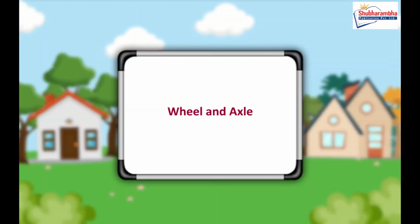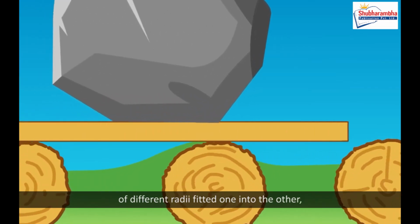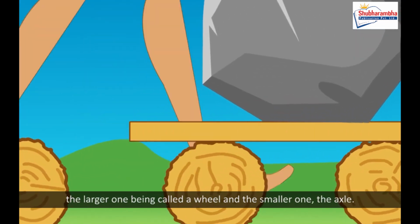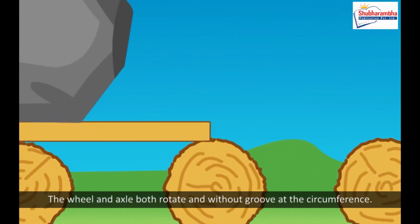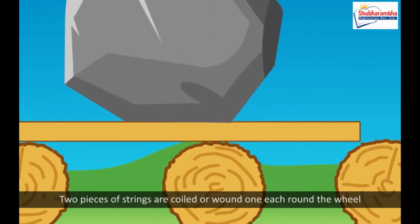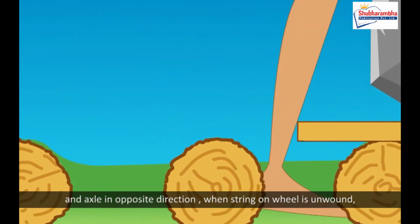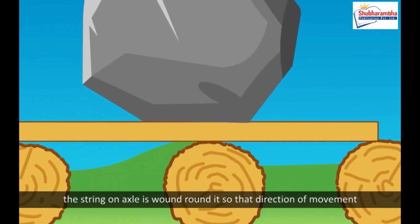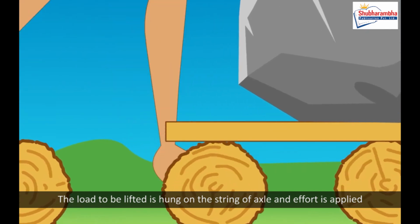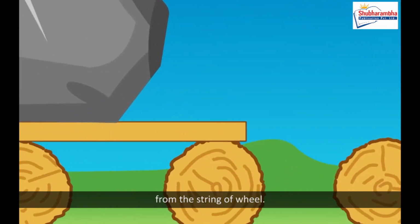Wheel and axle. A wheel and axle is a combination of two coaxial cylinders of different radii fitted one into the other, the larger one being called a wheel and the smaller one, the axle. The wheel and axle both rotate, and are without groove at the circumference. Two pieces of string are wound, one each around the wheel and axle, in opposite directions. When the string on the wheel is unwound, the string on the axle is wound round, so that the direction of movement of load and effort is opposite. The load to be lifted is hung on the string of the axle, and effort is applied from the string of the wheel.